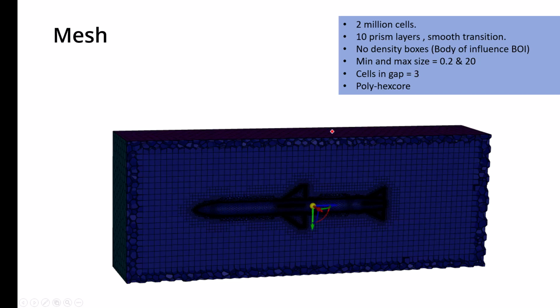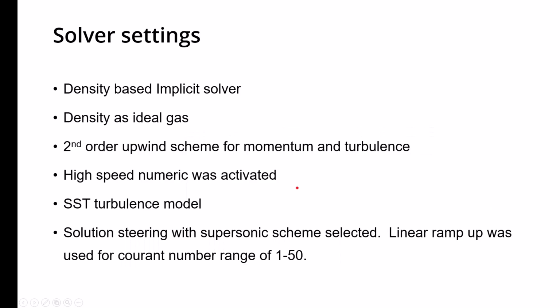So the edge length should be at least 0.6, since a size of 0.2 times 3 will be 0.6. But if the size is 0.8, it's not going to create 4 sets. These are the solid settings which I applied.